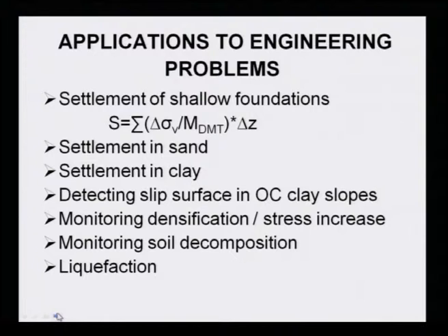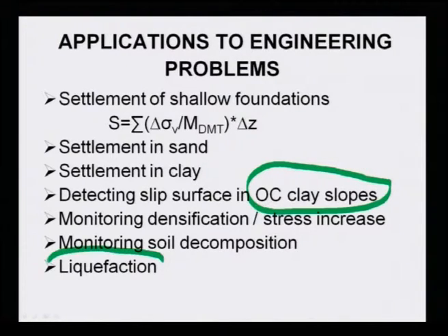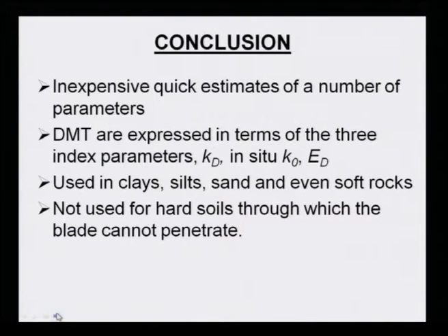Application to engineering problems: settlement of shallow foundation, you can also get settlement in sand, settlement in clay, then detecting slip surface in slopes, and as you are measuring pore water pressure, you can also determine liquefaction as well. It is a quick estimate, sometimes we say it is a quick test.